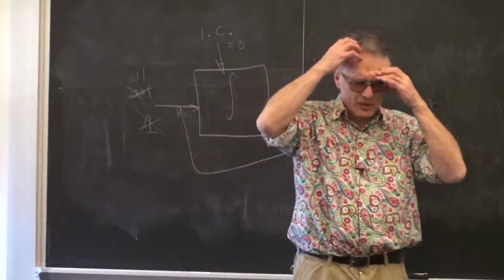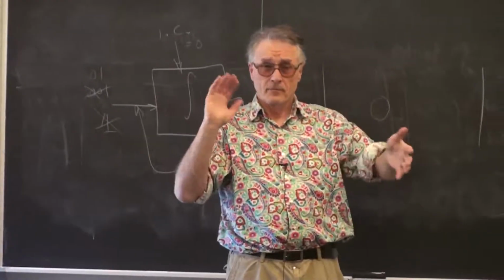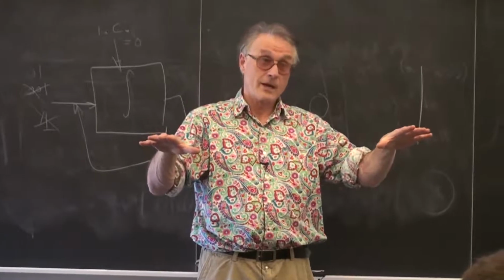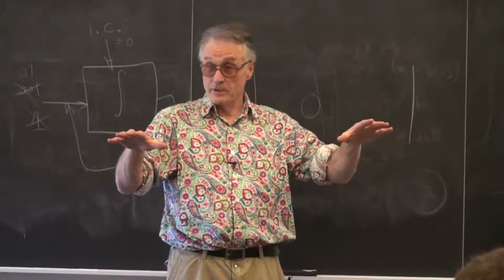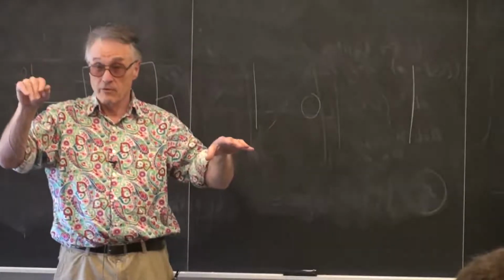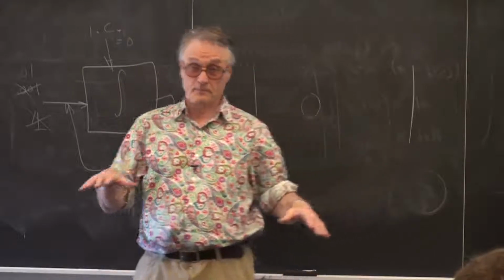Now, mixed up with all of this is you've got this long array that's being dynamically filled and emptied by these two threads. You better lock that array when you're doing the array operations, when you're doing the array write on the UDP side and the array read on the FPGA side.